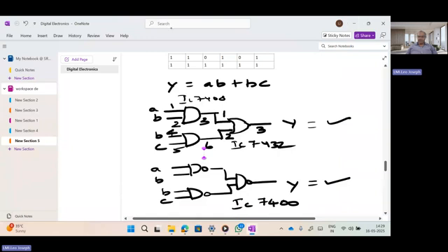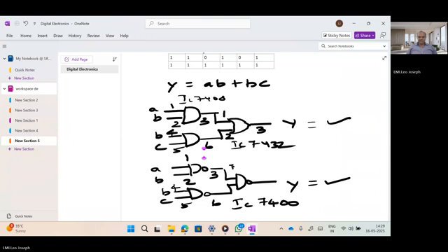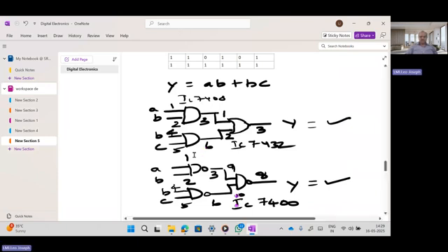So now I am going to write the pin diagram here. 1, 2, and 3. After that, 4, 5, and 6. And then 7, 7 is ground. So 8 is the output. This is 9, and this is 10. Like that I am writing. So 1, 2, 3 is the inputs directly from 1, 2, and 2 and 4 short. 5th pin is the direct input. Same thing here, 3 and 9 should be short. 6th and 10th should be short. 8 should be the output.